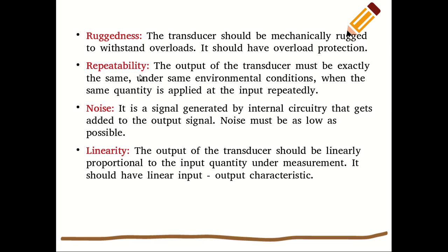Repeatability of transducer. Suppose I have taken a set of observations with a transducer. I have given some input and measured the output. Now, if I repeat the same thing again and again, then ideally the transducer should generate the same output each and every time. What we call the repeatability of a transducer. Noise is another parameter.